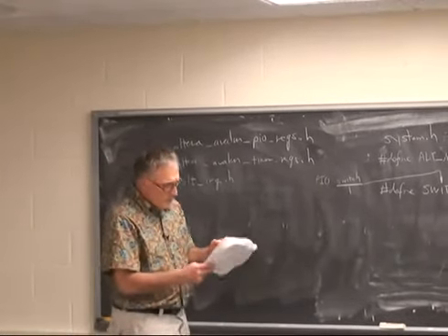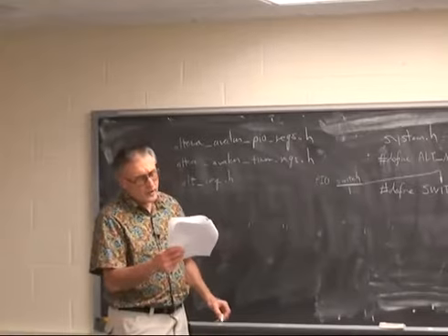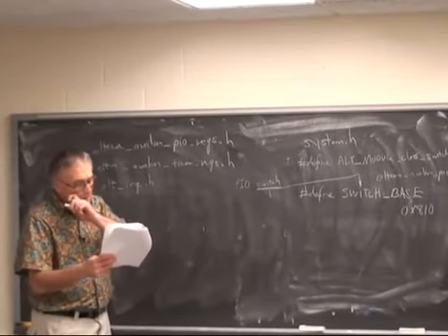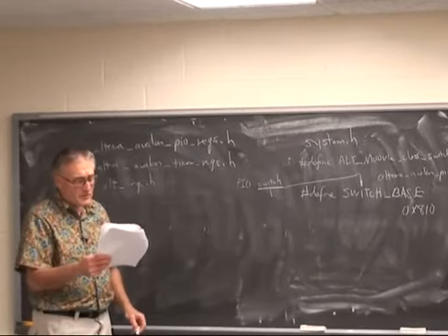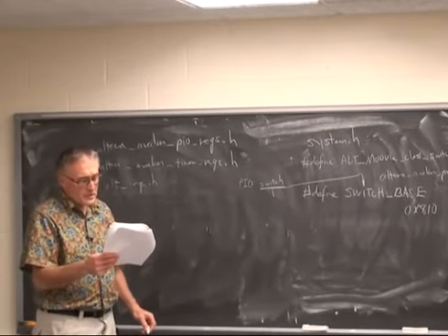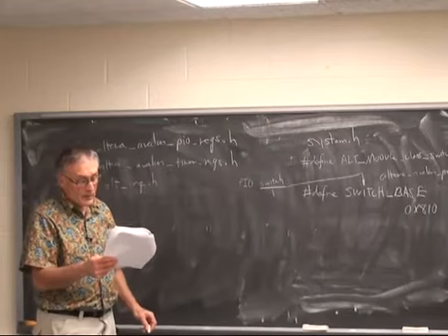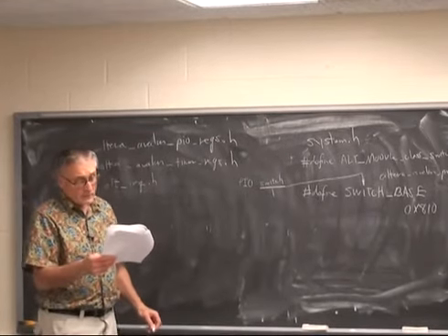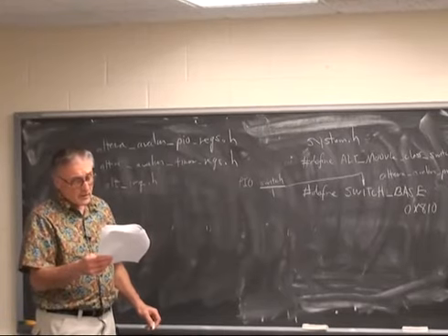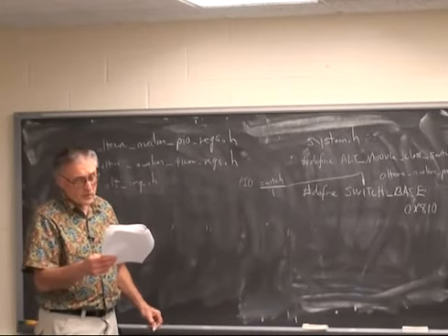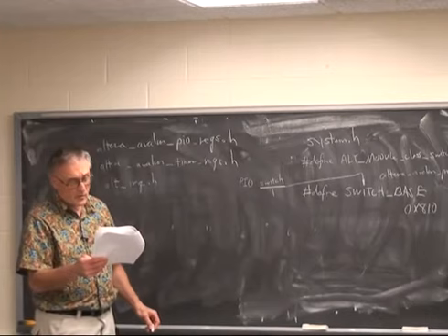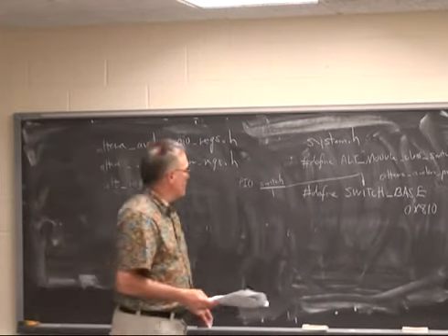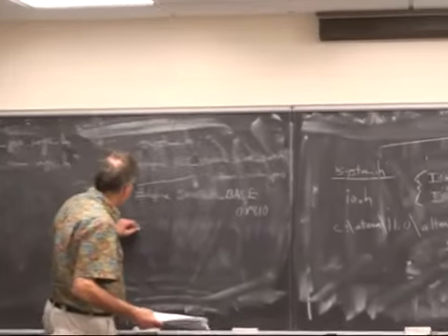And there's maybe 15 other defines. Define switch bit clearing edge register 0. Define switch capture 0. Data width 8. Oh, that's actually useful. This is an 8-bit port. Is there an interrupt associated with it? What's the interrupt controller ID? And the switch name.